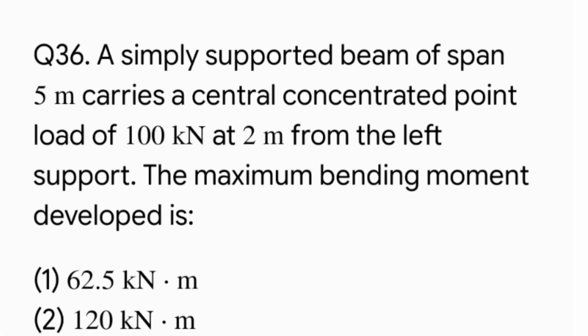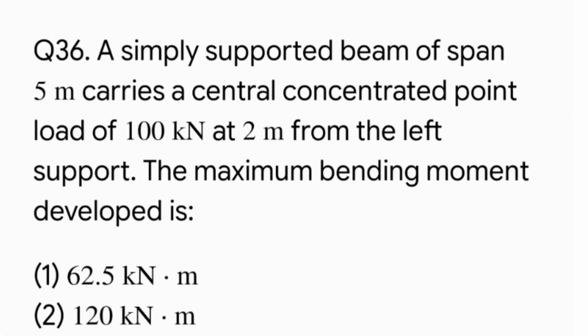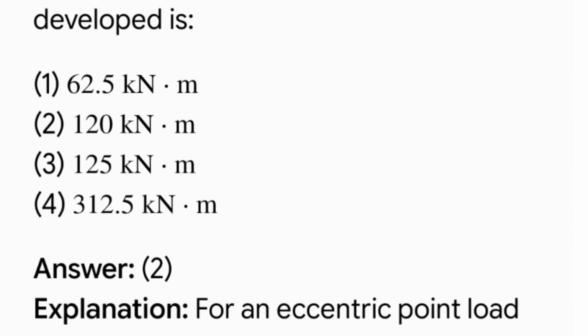Next question. A simply supported beam of span 5 meters carries a central concentrated load of 100 kN at 2 meters from the left support. The maximum bending moment developed is. Correct answer option 2, 120 kilonewton meter.